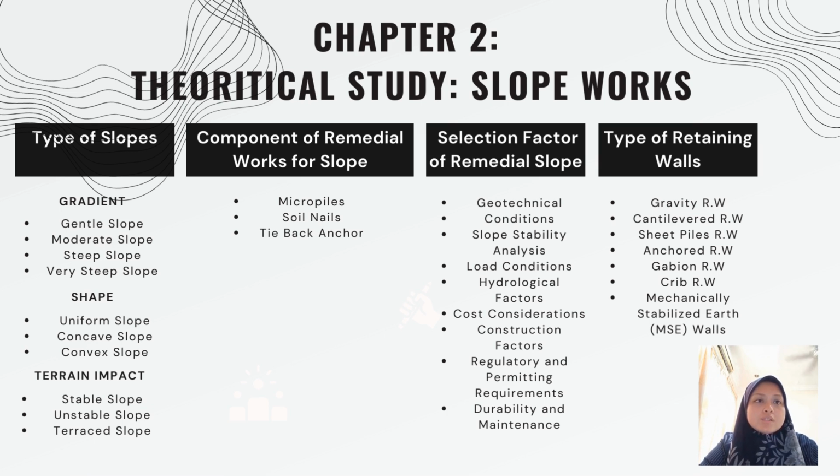Often used with soil nails, these anchors are drilled into the stable soil or rock behind the wall. They are tensioned to provide additional support, pulling the wall toward the anchor soil.